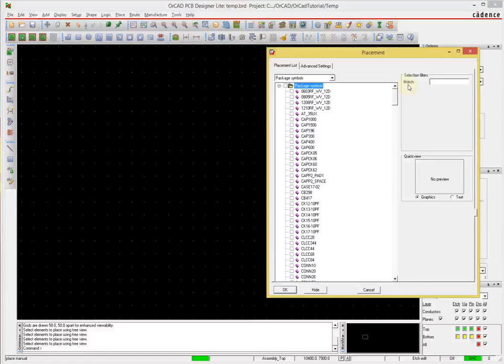And you're just going to have to go to see for capacitors. I imagine that the cap is what that means. And then there are some standard devices for surface mount devices, and you're just going to have to go through these. And this is the part where you need to be familiar with standard packages, what the traditional packages look like. But our interest is in DIP20. Our part is actually 14 pin.